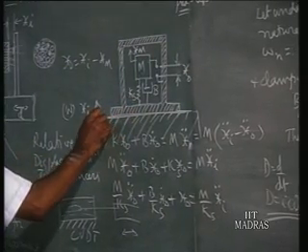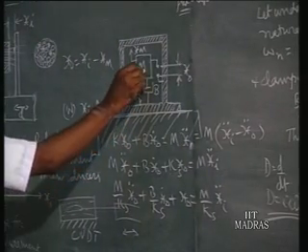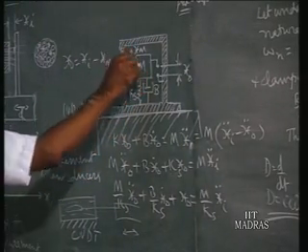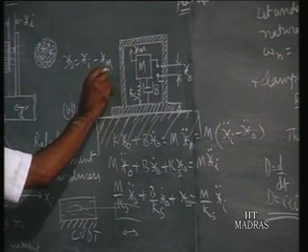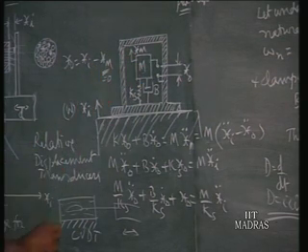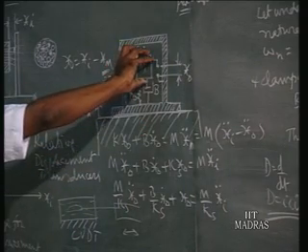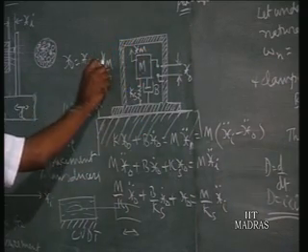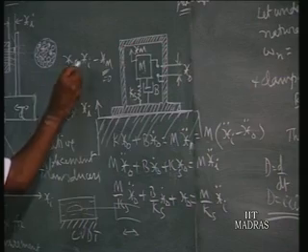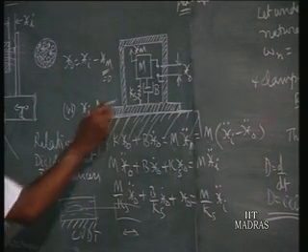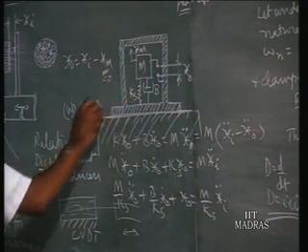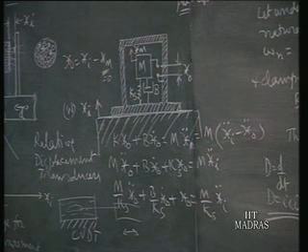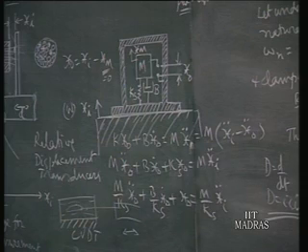It's because the higher frequency is very high, it is not able to move, so it becomes more or less static. So Xm becomes static. That means Xm is 0. It is unable to follow the vibrations. It more or less becomes static in space. When Xm is equal to 0, then we find Xo is equal to Xi. At that time, whatever Xo is, it becomes Xi. That is the physical explanation for this functioning of the seismic pickup for displacement measurement.